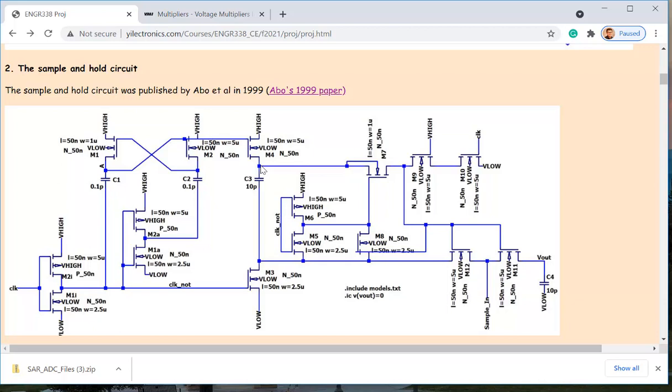Similar to the voltage doubler I just showed you guys, it has a base voltage stored over here, like VDD DC, and then it's adding that V in. So this will fluctuate based on the V in signal, right? It's going to be the same shape.